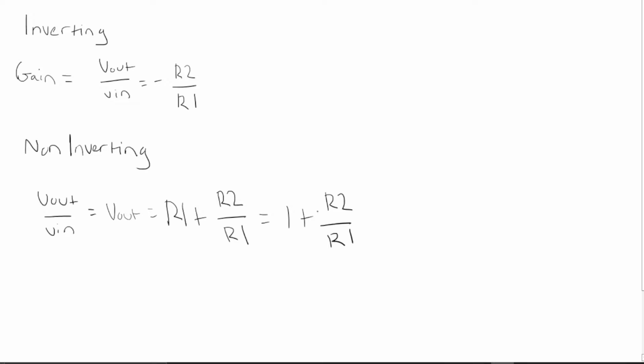And just a quick reminder what negative feedback is. It is the feedback looping back into the inverting pin, providing feedback voltage into the pin, allowing for the use of amplified signals as opposed to max saturation swings with the amplifier. If you do remember, one of the rules is that the op-amp will do its best to maintain a 0 volt difference in between the inverting and non-inverting pin.